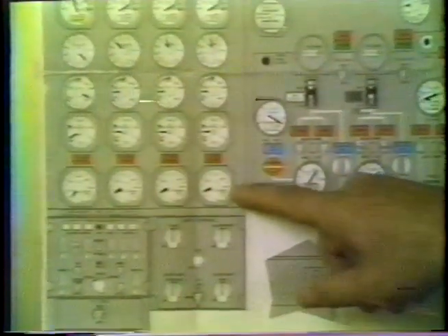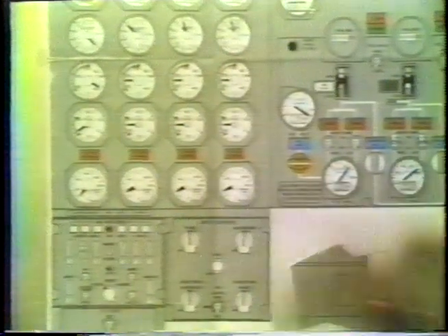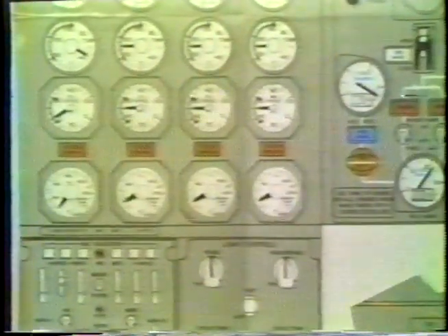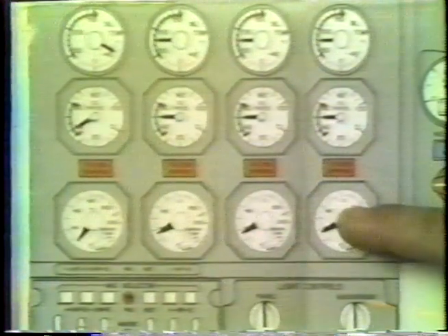I'm going to start down here at the bottom of the second officer panel and talk about the breather temp gauges. The gauges represent the temperature in the gearbox of the engine. There's been problems with air bypassing the various bearings in the engine and finding its way into the breather box and getting the oil so hot that they've had a few what they call oil box fires. These temperatures monitor that and indicate when that problem exists.